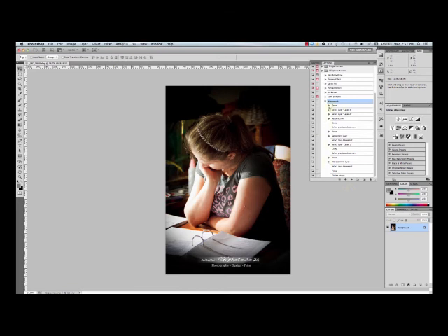Okay, it's important to remember, if I didn't mention, that you need to keep your template resource file that you're drawing information out of in a constant place with a constant name, because it's linking it here, showing the path to where that document is. If I move that document now or rename the document, this action will fail because it doesn't know where the document is. So create a folder in your drive called templates, and keep all your templates that aren't going to move or change in there.